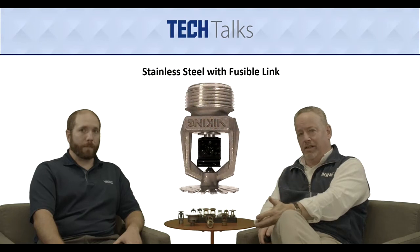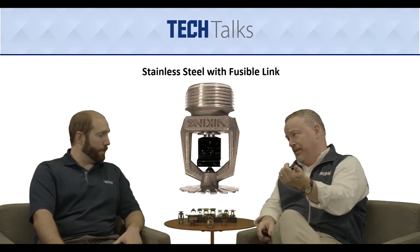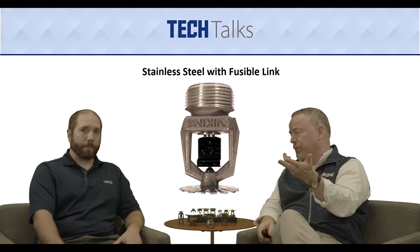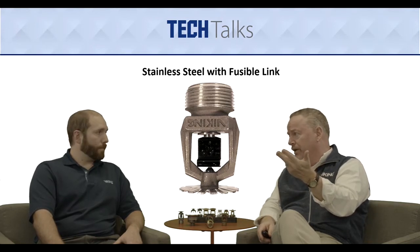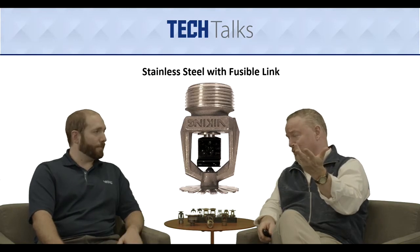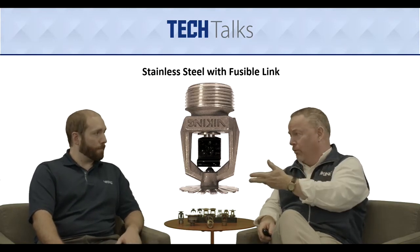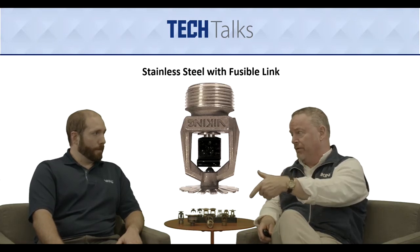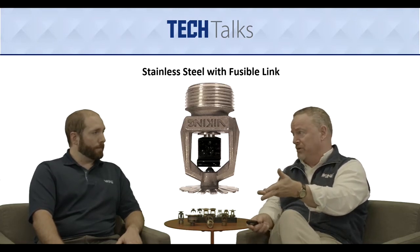So what type of sprinklers or coatings do we need to have? So the best one that we have, obviously the most resistant, is stainless steel, but this is a different type of stainless steel. So what's this got going for it in food processing that the other one doesn't? I'm noticing right off the bat that it's got a fusible link. But what's so good about a fusible link in this environment? Why can't we use a glass bulb?